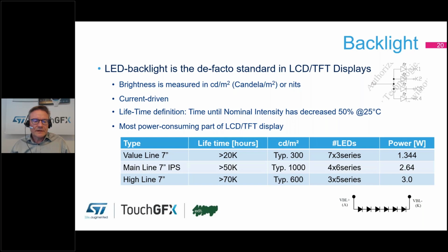So we have put together here a small table showing you the power consumption, because the power consumption in a display is widely defined by the backlight. It is by far the most power consuming part of the TFT display. So keep that in mind for the parts that will come later when we start talking about sunlight readability.